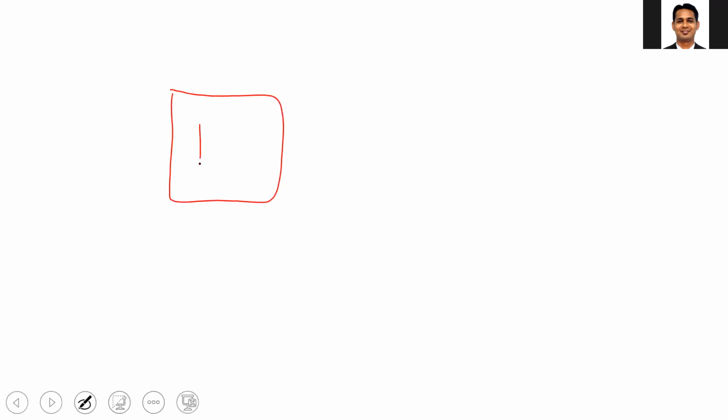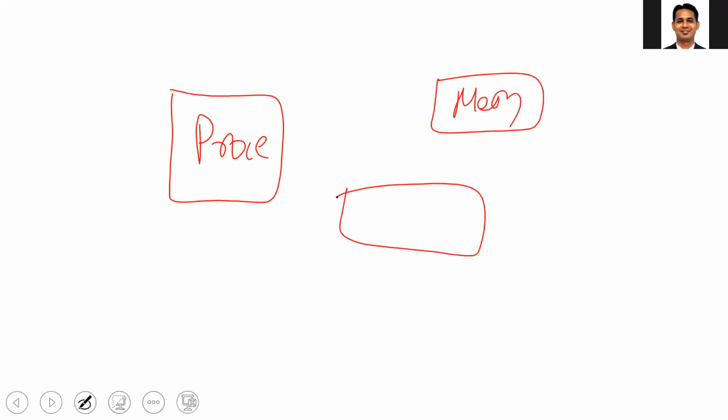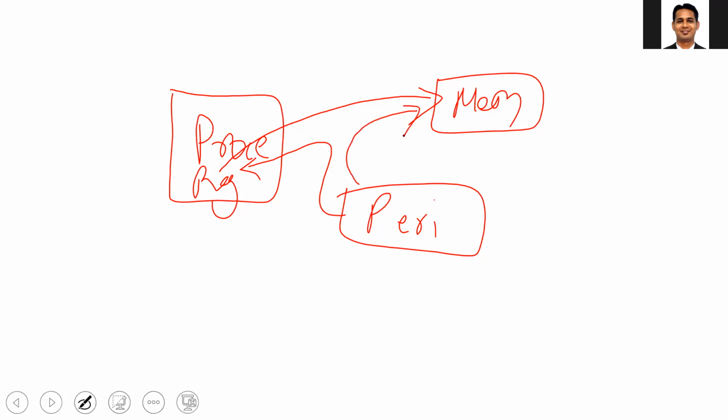So in such cases, why does the processor get busy or occupied with this memory task? Because what happens in such cases, you have the processor here, the memory here, and the peripheral here. The data is copied into registers in the processor, and from the register the data is copied into the memory. So you can see that the data has to be copied into the register, which is internal memory of the processor, and then it is copied to the memory. This is quite a long process. So we need to see if we can do better than this and transfer the data directly to the memory.